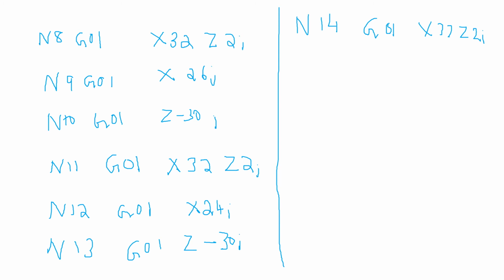Because as we have seen earlier, the workpiece goes 20, then 16, and 14, and then 10, right? So you will be going along 20. Once you make 14, then you will be going along 10, making the diameter from 14 to 10, and finally you will do the coding accordingly.